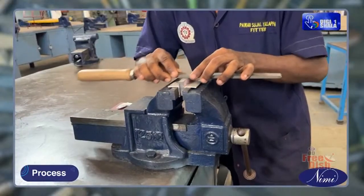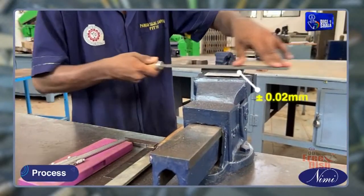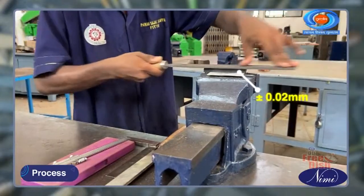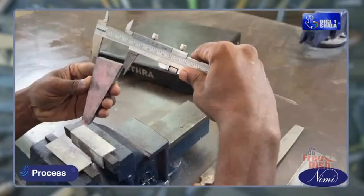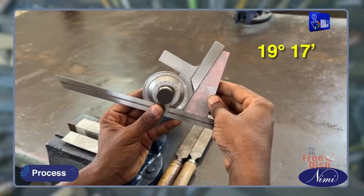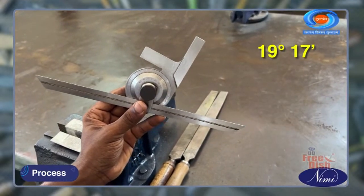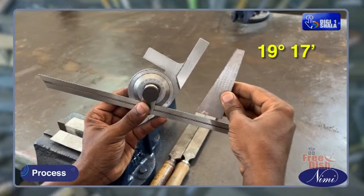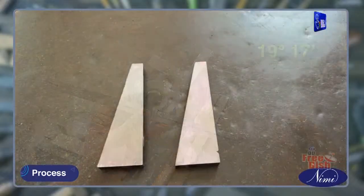File part 1 to size and shape, maintaining the dimensional accuracy of plus or minus 0.02 millimeters. Check the dimensions with a vernier caliper. Check the angle 19 degrees 17 minutes with a vernier bevel protractor. Similarly, file part 2 to size and shape and also to angle 19 degrees 17 minutes.